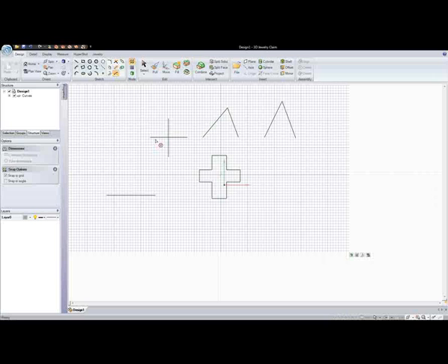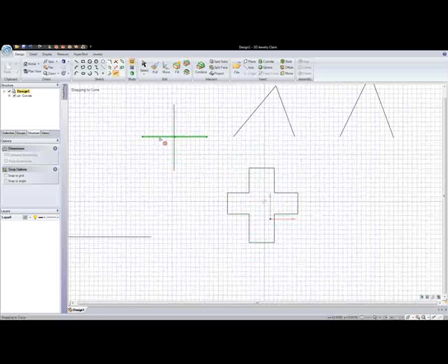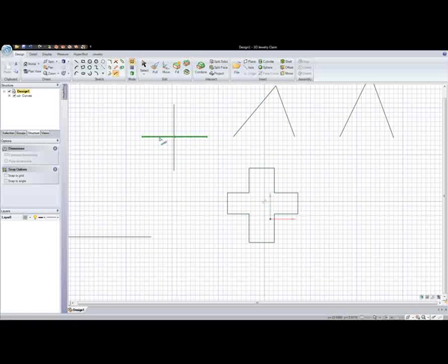Below that, we have split line. We can split a line either by a point or with another curve. So I can left click on the line that I want cut, and then the icon changes on the mouse and becomes a saw. So if I left click on this curve, it'll now cut my line from that curve. Next, I can cut my curve if I left click on this from the mid, the triangle, and now it's split into two.